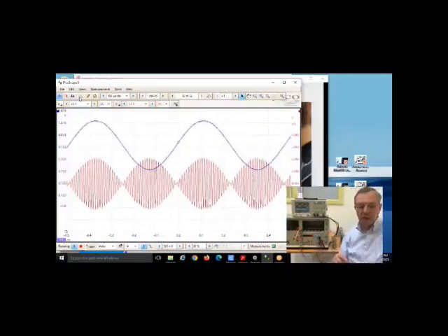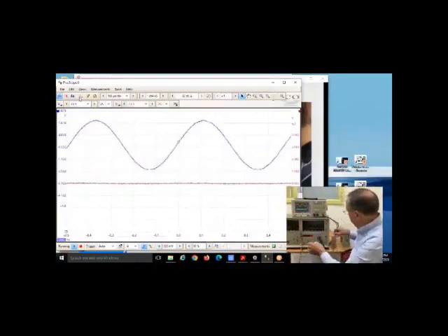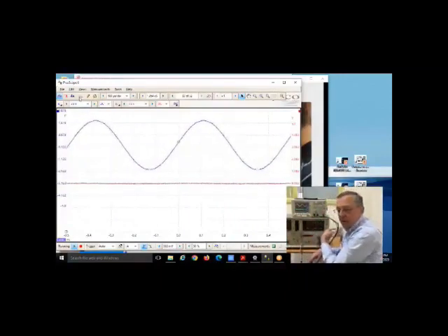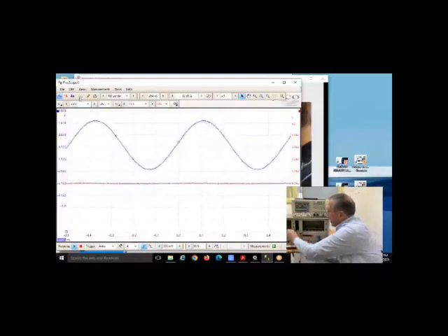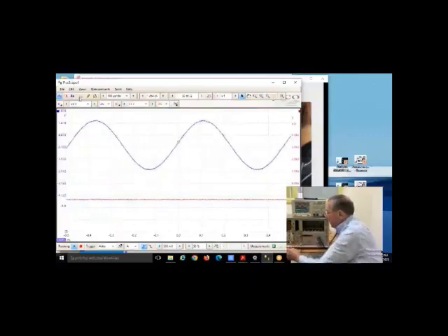Let's finish this session by using 2 modules to build an experiment. So let me disconnect everything. So I will now, again, take the adder, remembering that any module can be in any position in the rack, and they're all hot swappable. So for this adder, what I'll do is I'll take this 2 kilohertz message you see, and I'll put it to one input of the adder. The other adder input, I'll take variable DC, and I'll patch that into the second input.